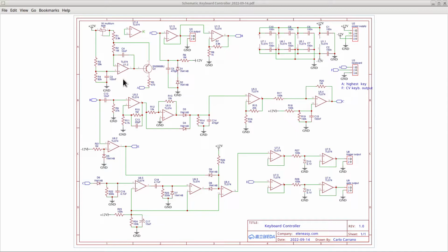Here just notice that the generator is made out of U1.2 and Q1, along with a few polarization resistors and a couple of feedback resistors to add a negative feedback to the op-amp to prevent auto oscillations. Trim pot R29 takes care of tuning the current we need for the whole array of resistors, regardless of how long it is. The second improvement may not be obvious, but it is very important.